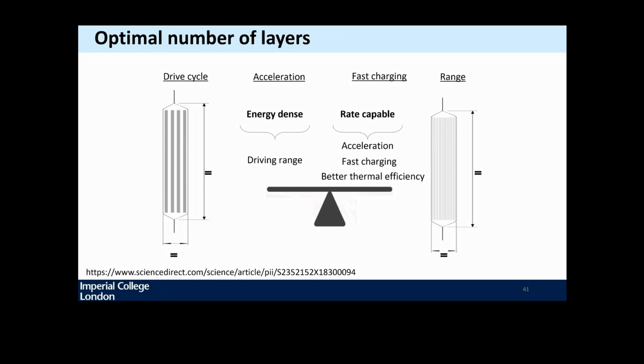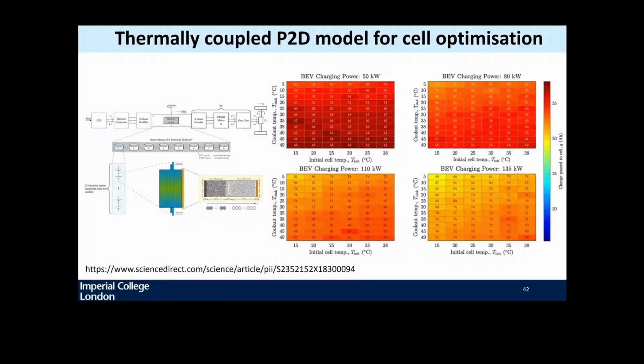And so this is a paper written a few years ago, where we basically went from a powertrain to look at the request on the battery pack, to split the battery pack into cells, to end up at the level of what an electrode pair would see in terms of power requirement. And then we used a thermally coupled model, like the continuum model I showed you before, but now with heat generation and with everything dependent on temperature.